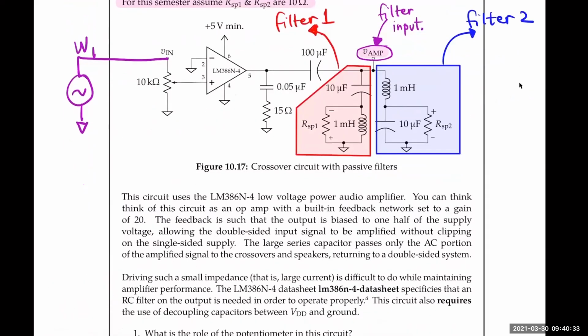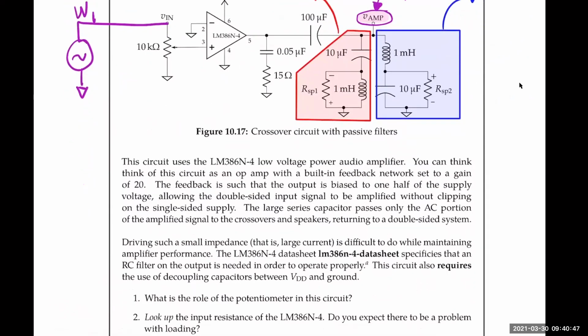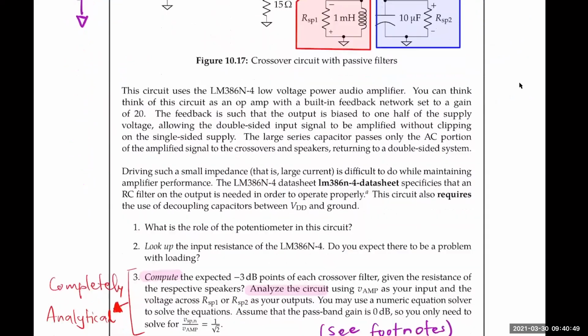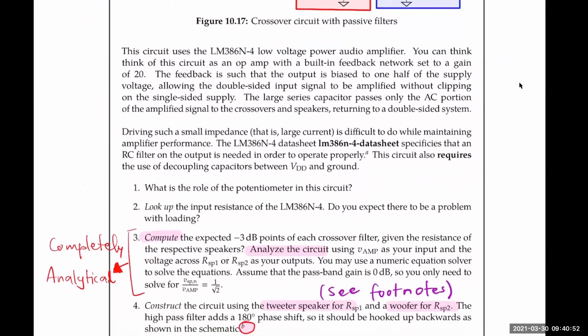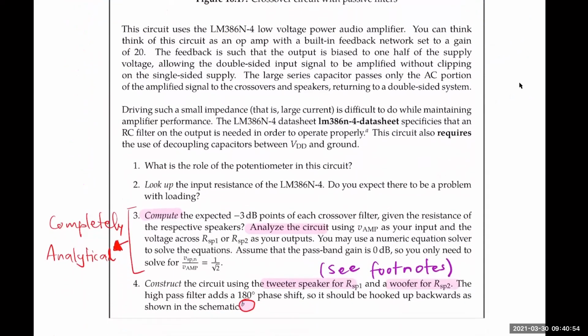So for this, you'll be using an audio amplifier called LM386. Now, be careful. This has a very different pinout compared to the pinout for the other amplifiers that you've used before. So be careful and look up the pinout for this particular audio amplifier.